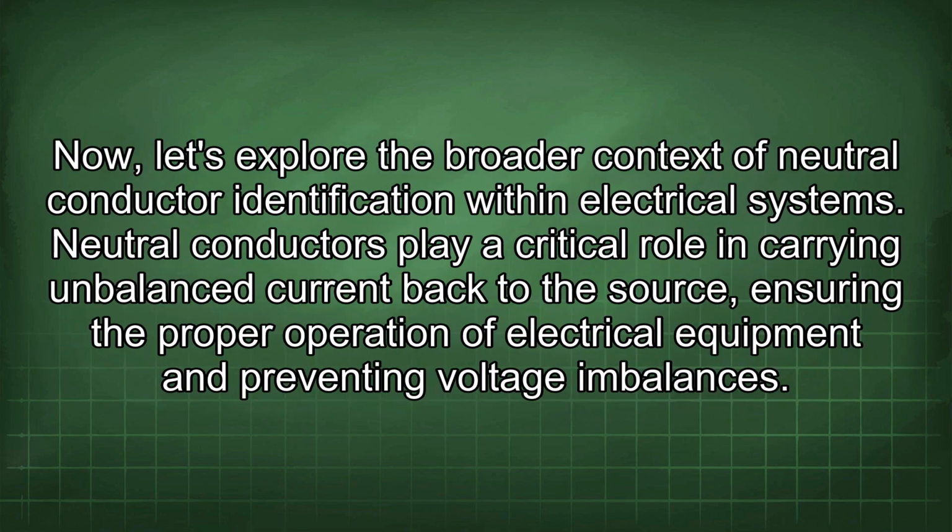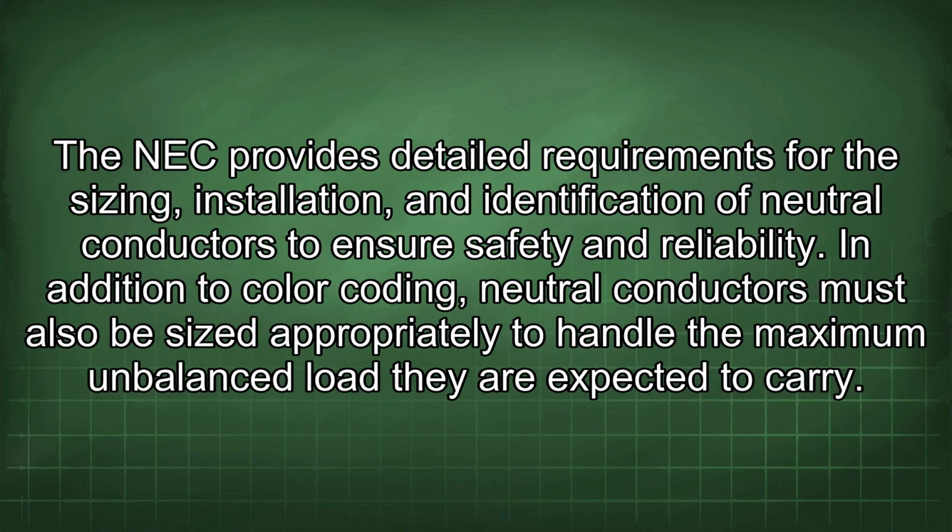Now let's explore the broader context of neutral conductor identification within electrical systems. Neutral conductors play a critical role in carrying unbalanced current back to the source, ensuring the proper operation of electrical equipment and preventing voltage imbalances. The NEC provides detailed requirements for the sizing, installation, and identification of neutral conductors to ensure safety and reliability.